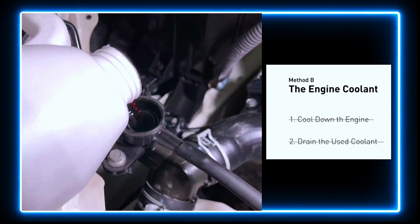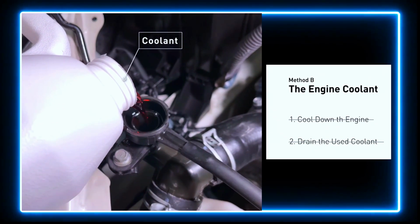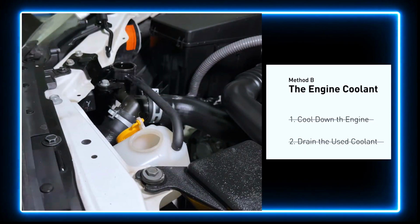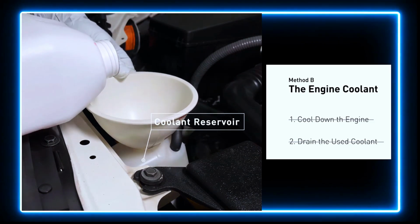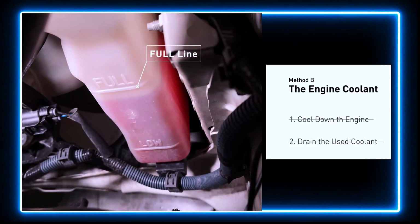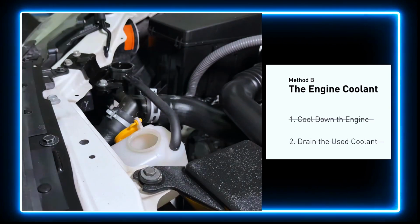Next, add fresh coolant to the radiator until it reaches the base of the filler neck. And then take off the cap of the coolant reservoir. Fill it with fresh coolant, not exceeding the full line. Then replace the cap.